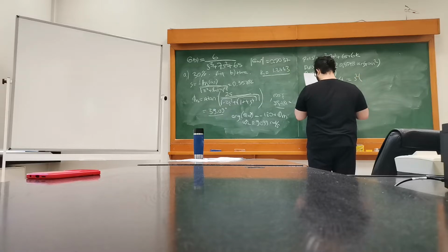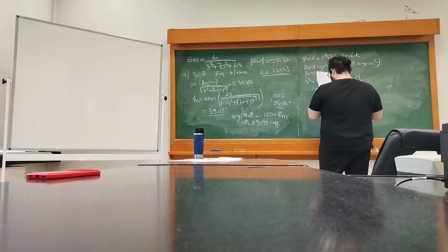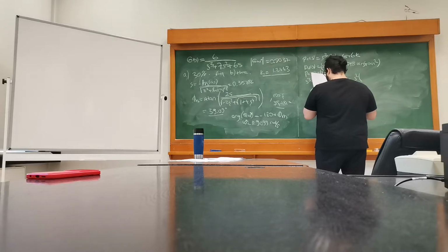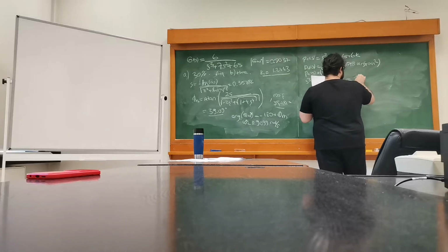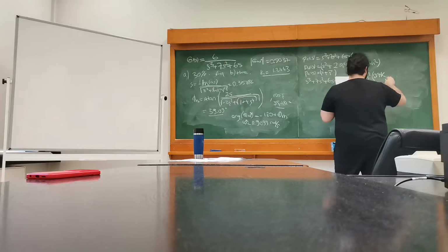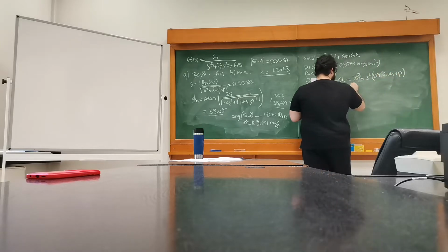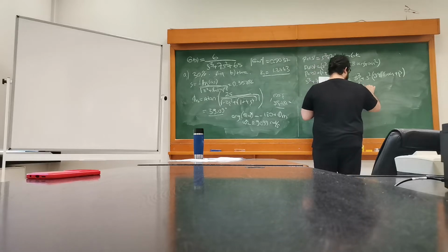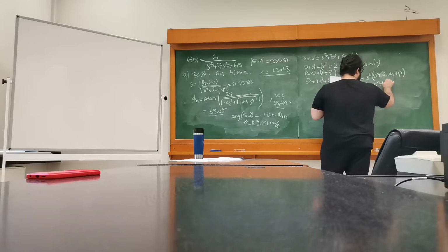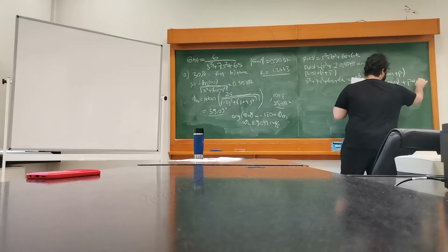So it's s cubed plus s squared times 0.716 omega n, which is 2 times 0.3578 omega n, plus p, and plus s times omega n squared plus 0.716 p omega n, plus p omega n squared.